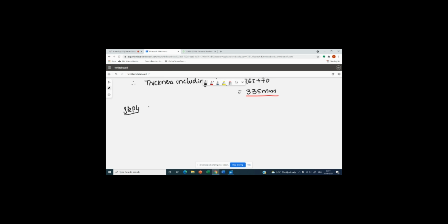Now step four will be the calculation of loads on the slab. So the first and foremost load is the self weight of the slab. As we all know, the load will be acting on an area, so we have to multiply the density with thickness. Which thickness? One is the thickness of the flat slab away from the drop, the other is the thickness near the drop.